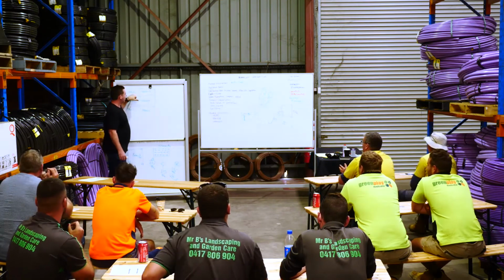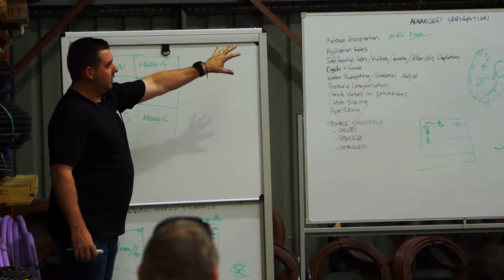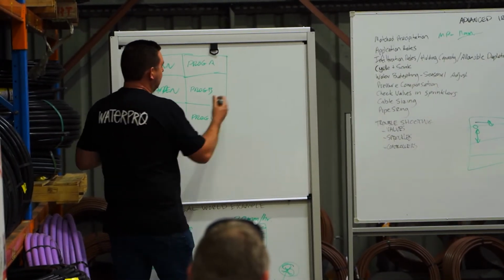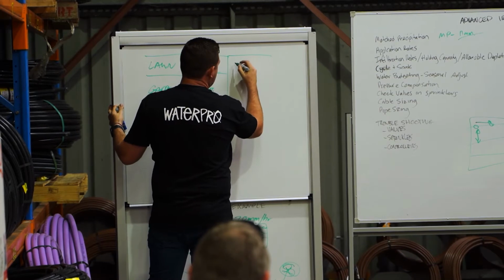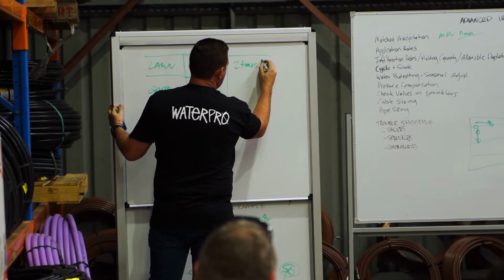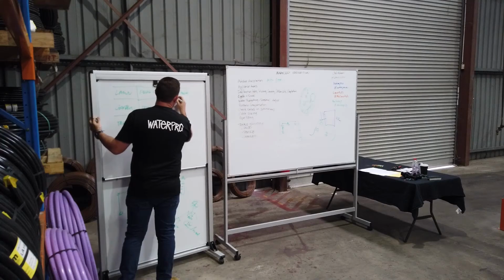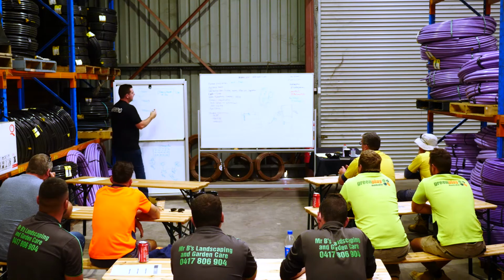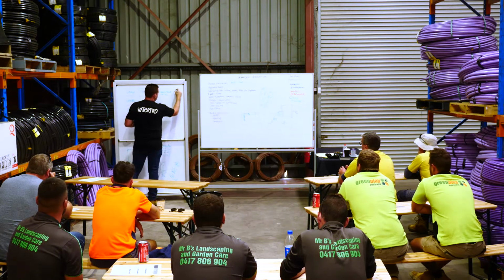So with the lawn, we know that it can take 10 to 18 mil, so we don't need to try and cycle and soak that one. So we can say that we're going to water that 2 times a week at 1 hour. Well, that gets us to 22 mil, right? So that's not enough. We need 25 mil for a lawn.